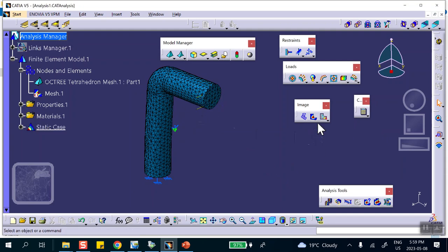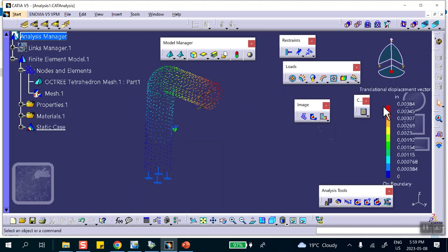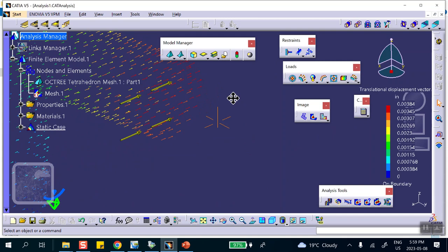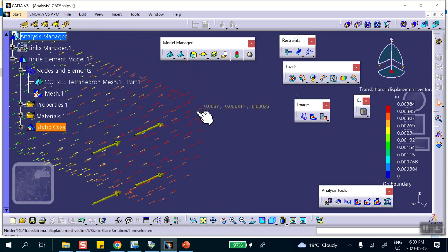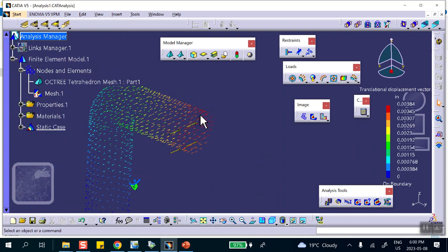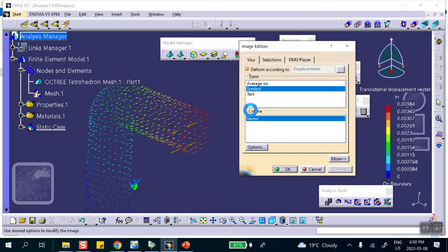Now, you want numbers? You click on this icon, displacement. This was deformation, just gave me a change of shape. This is displacement. You click on it, and notice that if you zoom in, you see these arrows. So that node goes in that direction in the XYZ by this amount. And in fact, this is fine. There's nothing wrong with it, except I'm going to change this.